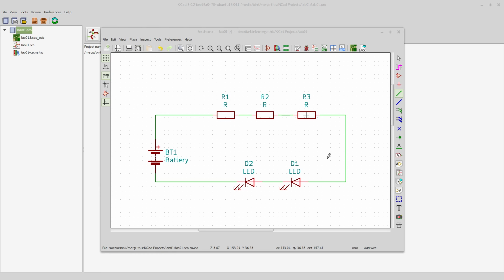And a net list is a text document that's going to tell us all the components that we're using, their associations, and what's connected to what. Okay? Some other programs utilize net lists as well. You could do a net list here, and you could maybe import it into, say, a Spice program or something, right? So that's our next thing. And so if you look around here, here's our net list. Looks a little bit different than it used to, but that's fine.